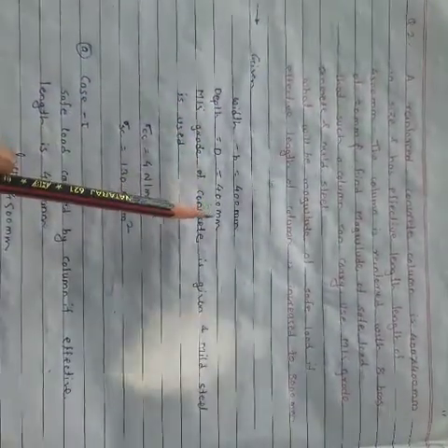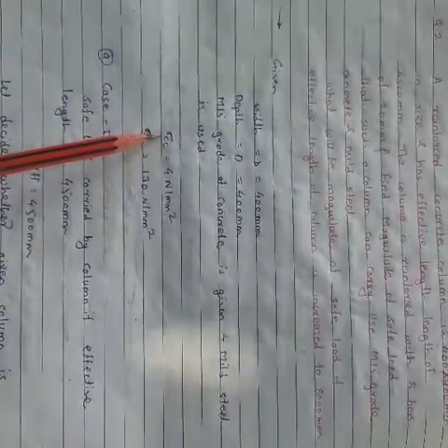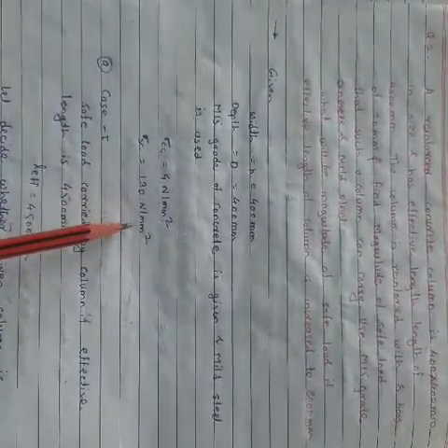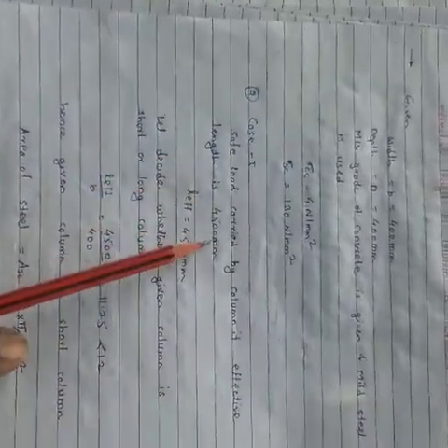So first, the width of the column is given as 400 millimeter, and the depth of the column is also equal to 400 mm. Then M15 grade of concrete and mild steel are given, that is, the materials are given. After referring to IS 456, we get the permissible stress in concrete under direct compression equal to 4 Newton per mm square, and similarly the permissible stress in steel is equal to 130 Newton per mm square for the mild steel. Now case number 1 is the safe load carried by the column if the effective length is equal to 4500 millimeter. So L effective is equal to 4500 millimeter.